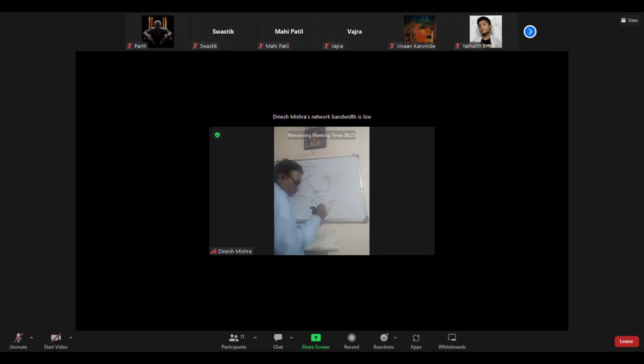When the fluid moves, it produces opposition to the vane movement. When the deflecting force works and the controlling force works, this fluid will oppose. So when the moving fluid produces opposition to the vane movement, damping force is produced due to fluid friction.